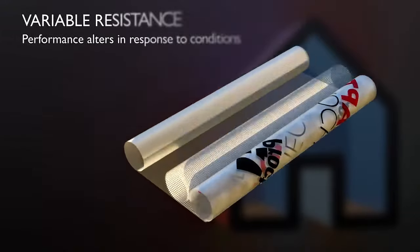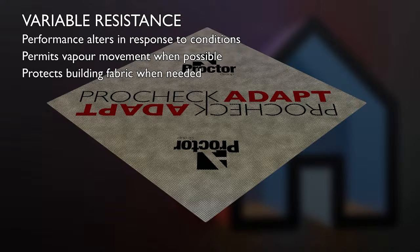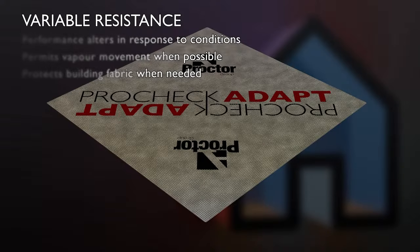Another type of AVCL to consider is the variable resistance membrane, such as our ProCheck Adapt. Membranes of this type have a range of vapour resistance that can alter in response to their surrounding environment. This is useful because it allows moisture vapour to move through the wall more easily when conditions allow, but still protect the building fabric when necessary.